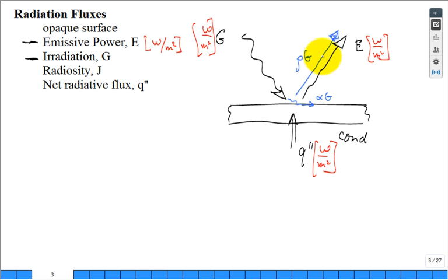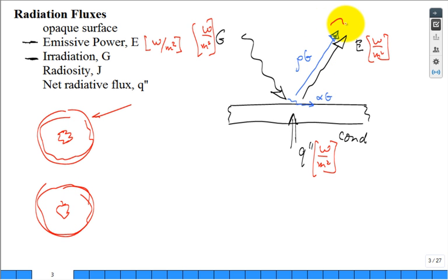And now you're saying, I have some part of the photons coming off of a surface are due to the emission. Some of the photons coming off of a surface are due to reflection. And the net outgoing is called the radiosity. Radiosity. New word. Hey, this class is just all new vocabulary, isn't it? Well, sorry, engineers try and make it as simple as possible, but then they have to have new terms and new words to quantify the stuff. Radiosity. And the symbol J is used for the outgoing net flux.